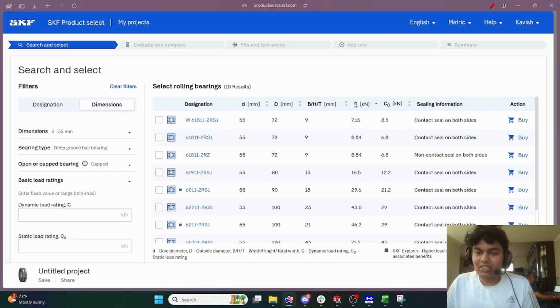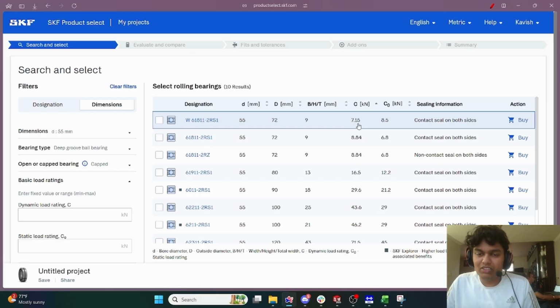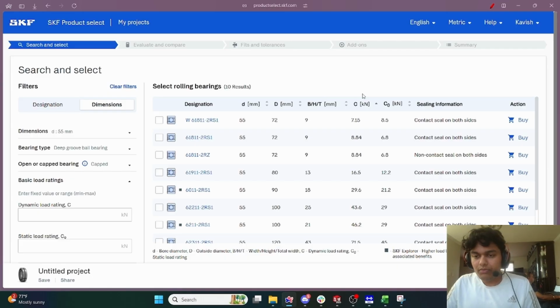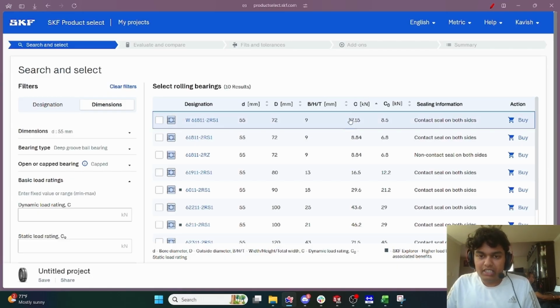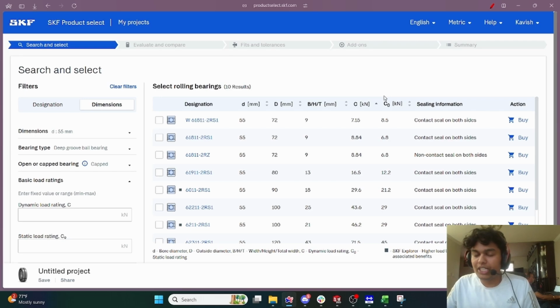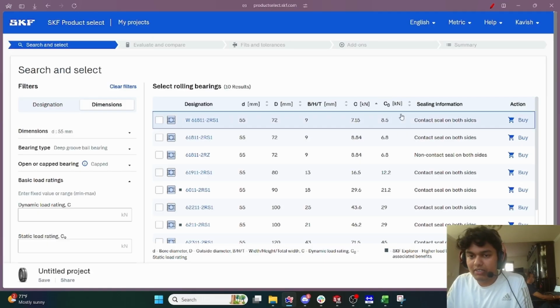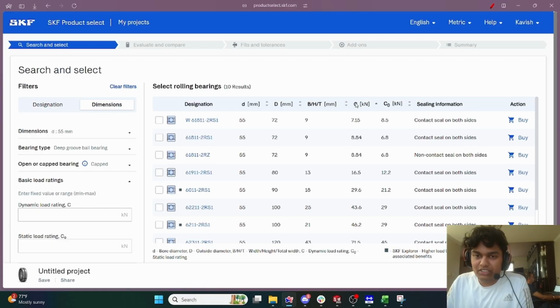This is without taking into account some factors, but in general, that's 1 million revolutions, which isn't actually a lot for a bearing. This is the number we care more about because our entire drivetrain is always moving faster than at least 100 RPM. You're never going to go much slower than that. So you can effectively ignore C0. Keep it in the back of your minds, especially when we talk about the output shaft. But for now, just consider C.